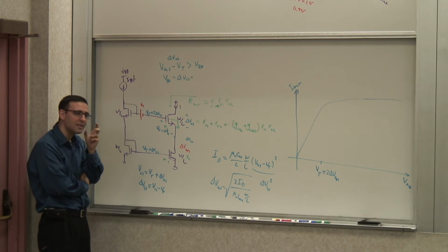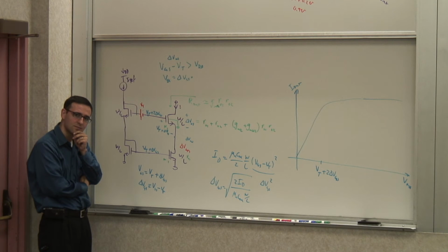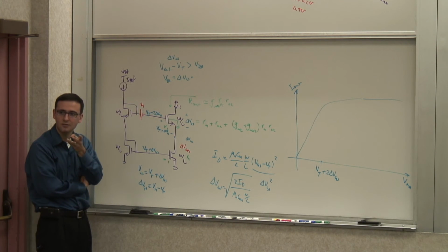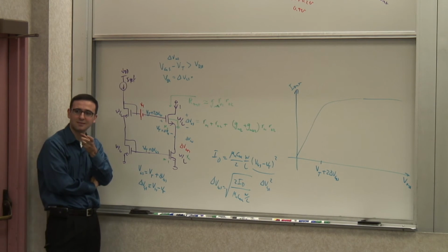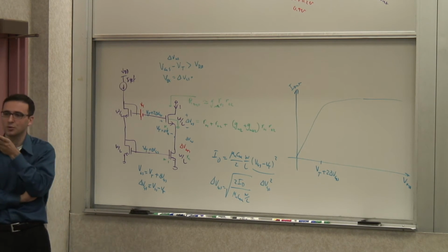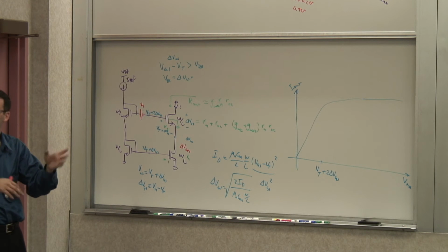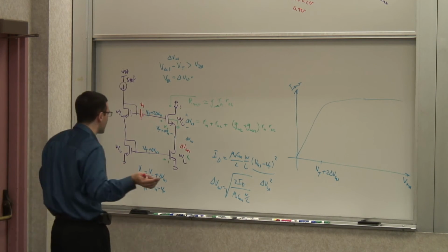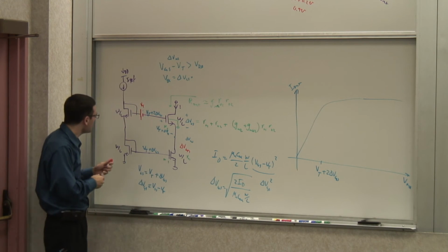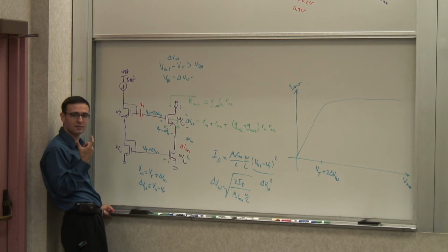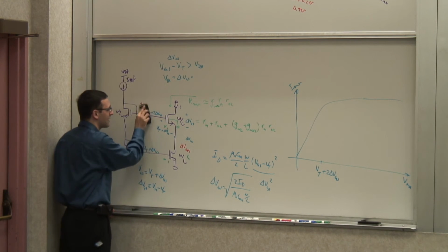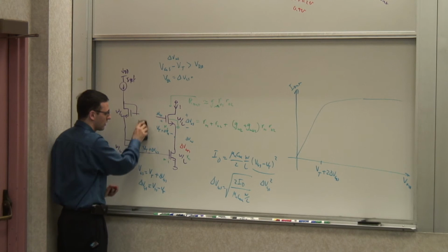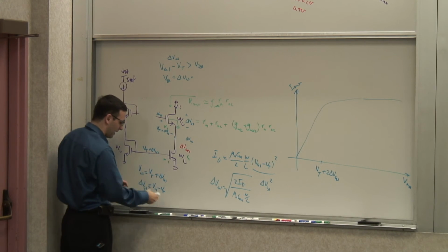Well, what gives me a VT drop? Well, a MOSFET, right? The resistor, you say the resistor, but I'm trying to match the voltage across a resistor to a VT. Those are two completely different kinds of thing. Maintaining that over all sorts of variations is almost impossible. So I have to get it out of another MOSFET, right? The gate-source voltage, in principle, could help me here.